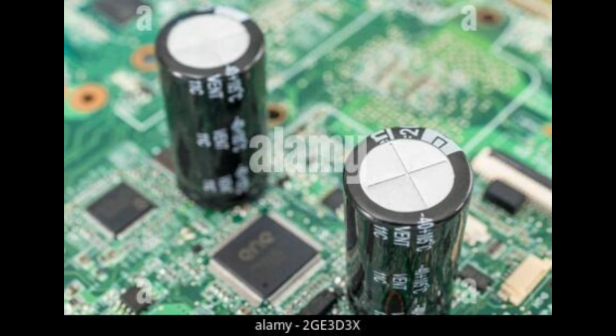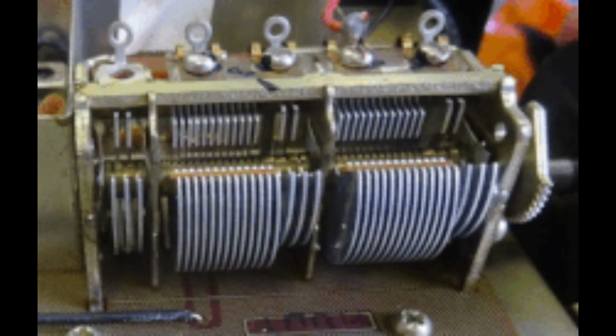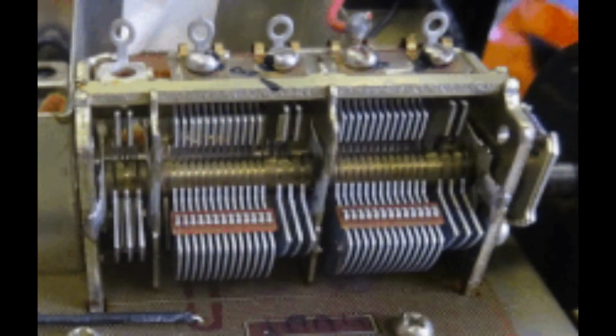The electrolytic capacitor is a type of polar capacitor that uses the electrolyte as one of the electrodes to maintain heavy charge storage. The electrolytes can be solid, liquid, or gas type material. Such types of capacitors have high capacitance values ranging from 1 microfarad to 47,000 microfarad, and they are only used in DC circuits.